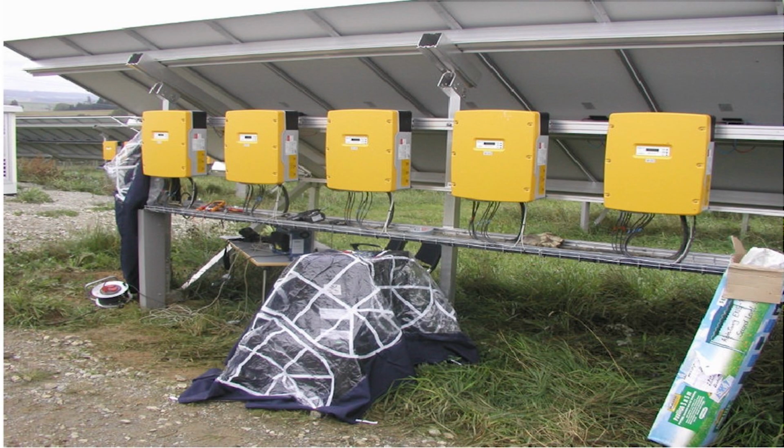Microinverters are set up in the opposite manner as a string inverter. Solar PV systems with a microinverter have an individual microinverter attached at the side of each solar panel. Whereas string inverters send energy from every panel to a single inverter, a PV system using microinverters converts the DC solar energy to AC energy on the spot.